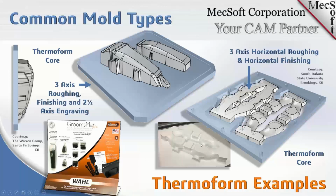And then on the right, we have an example from South Dakota State University of a student project where the core components are machined out of stock material, and then they're set on the thermoform machine, and then the plastic is formed over it. So thermoforming, like I mentioned, is the least amount of accuracy that you need to worry about, primarily draft. So you want to make sure you have enough draft to get that plastic up off of that core.